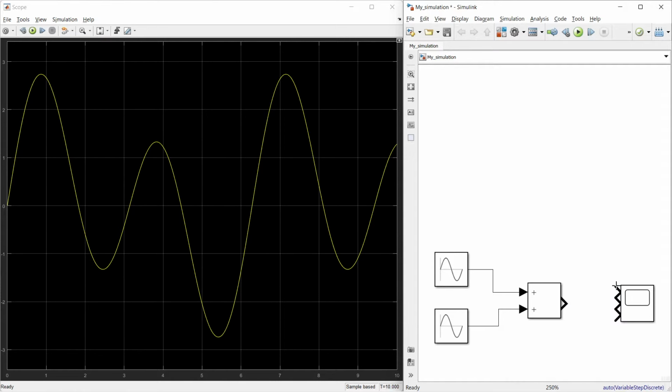So what we'll do, by dragging you can increase the size of the scope. You can connect this signal to the scope by left clicking over here and dragging it up to the signal. Another way is, if you want to take a branch from here, then right click at this point, drag a branch, leave the right click, left click, drag it to the point. So this is another way through which you can take a branch out from any signal.